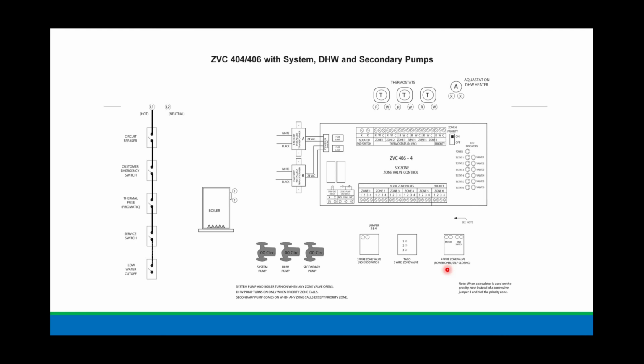Again, there's a low water cutoff in the line voltage, so that's a 120 low water cutoff. And we bring power to one side of the transformers. To finish that, L2, that's your white wire, we bring to the other side of the transformers. You see the two dots, those are wire nuts.